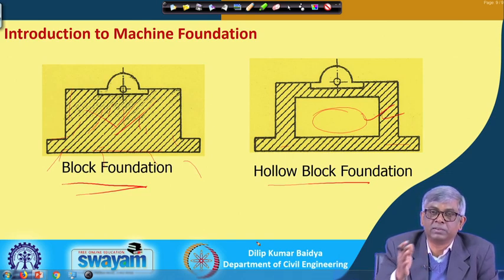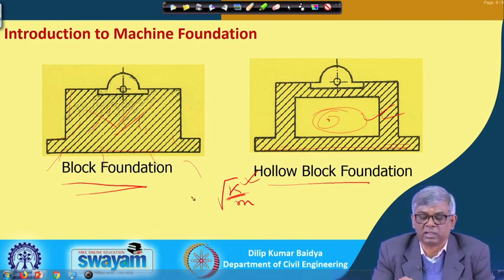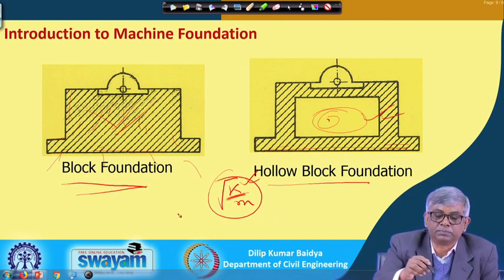Sometimes you have to reduce the natural frequency, sometimes you increase it. So, by doing this, under root k by m, area increases, so k is increased and mass is reduced. Of course, this has to be optimized. If mass is reduced, then natural frequency will be increased. So, some adjustment has to be done by this process.